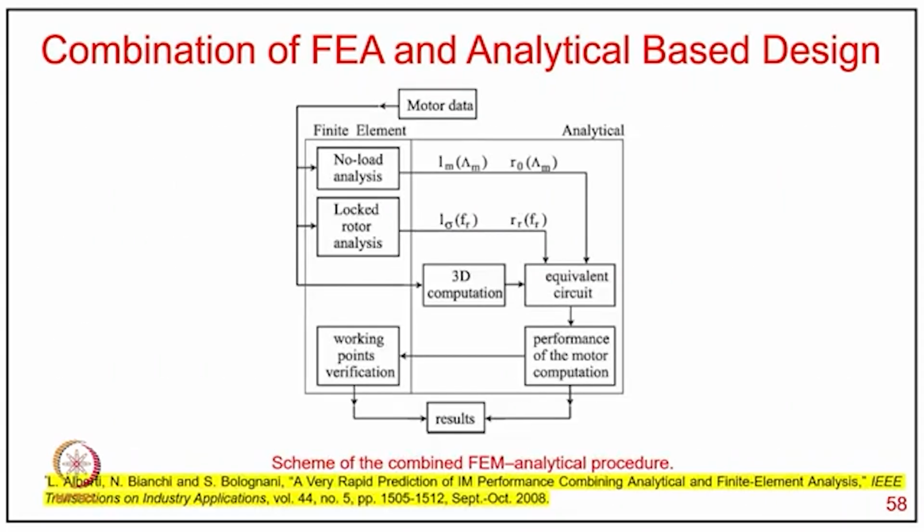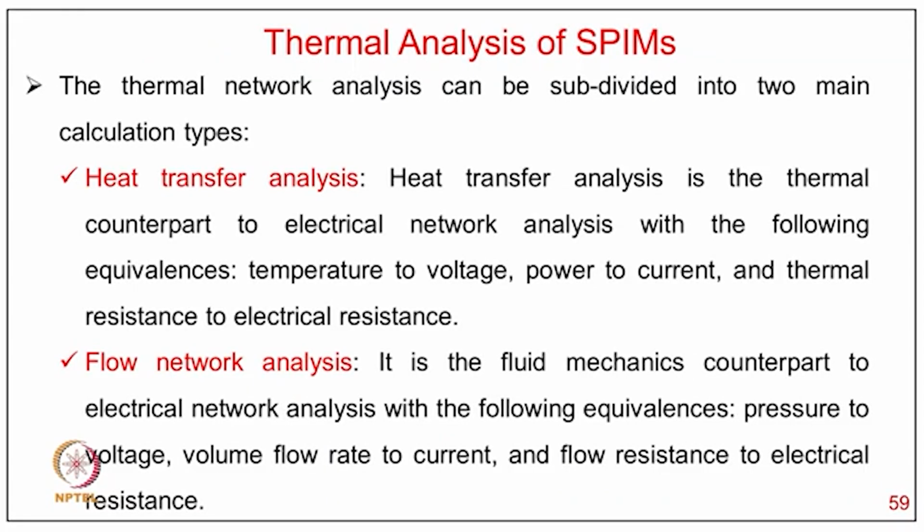So this is typically a scheme of the combined finite element analytical procedure, which starts from motor data, then we go to finite element analysis for typical calculation of no load, locked rotor and working verification, and then of course analytically we calculate the equivalent circuit, then the performance computation with the equivalent circuit from the 3D calculation, and the performance calculation, then verification of the results.